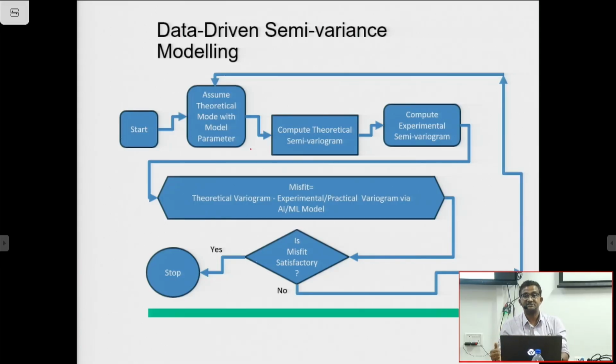In fracture detection, let us say, fractures can be in any direction, and their orientation largely affects these hydraulic properties. In what directions the fractures are there has to be explained, so you need to properly deploy the correct interpolation method. Then only can you capture the anomaly.